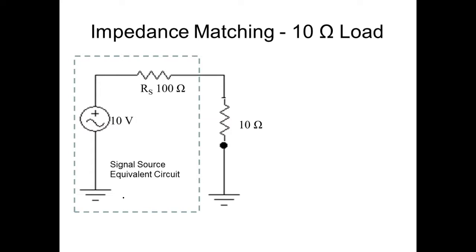So here the load is out there. That 100 ohm is representing the internal resistance of the source. So this would be like the internal resistance of a battery. Have you ever gotten a battery and measured across the output when it's new? It's going to measure about 1.65 volts. As soon as you load that down, that voltage is going to drop. Why? Because of the internal resistance of the battery.